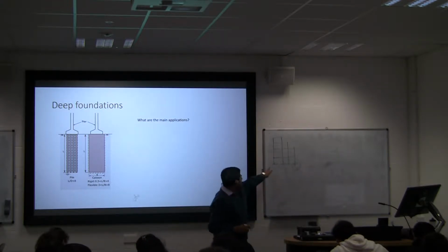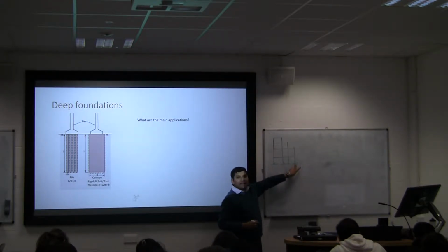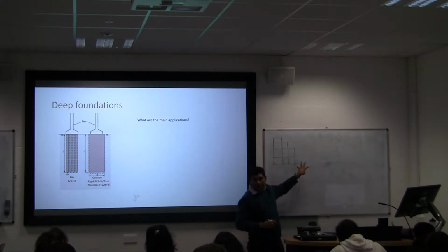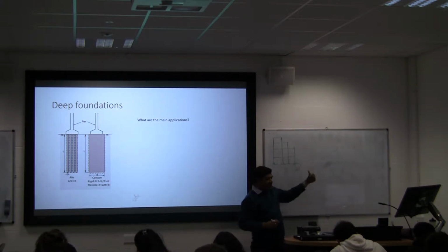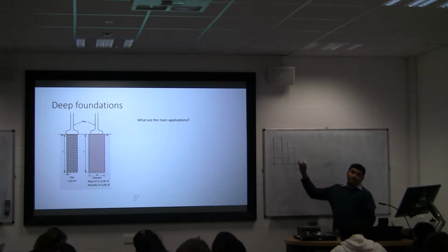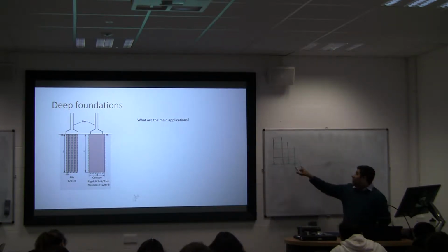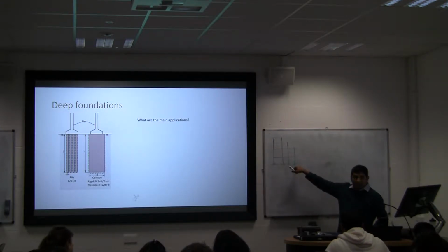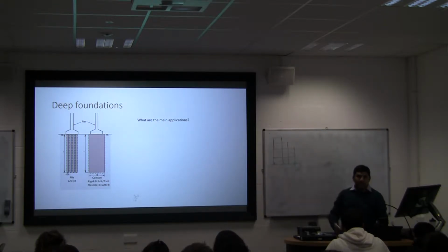In analysis, if I assume it to be fixed here or hinged here, you have to make sure that you do a connection which is compatible with what your assumptions are, because the reactions you will get will be a function of the boundary condition. If you assume it to be fixed and apply the loads based on fixity, that is something else. If you assume a moment, something else.